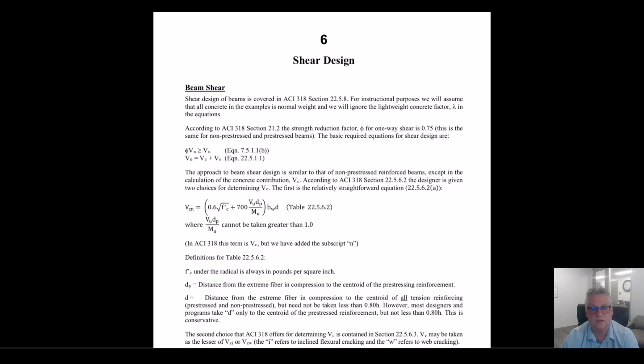The post-tensioners just decided to adopt what the pre-tensioners had done for shear, even though I am going to demonstrate, or you're going to actually demonstrate in the homework assignment, that it really doesn't make any sense to have done that. We don't have simply supported members. We have continuous members, and our inflection points or our zero moments are not at the supports. They're at inflection points away from the supports, and all those things are going to cause problems. But nobody's cared enough to change it.